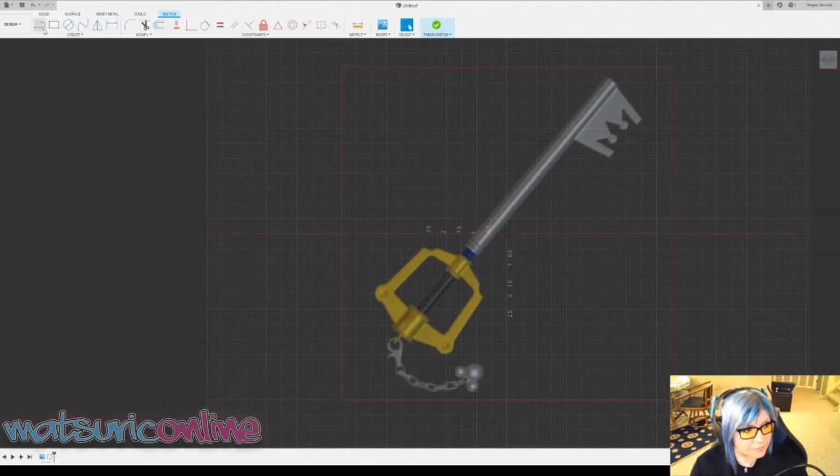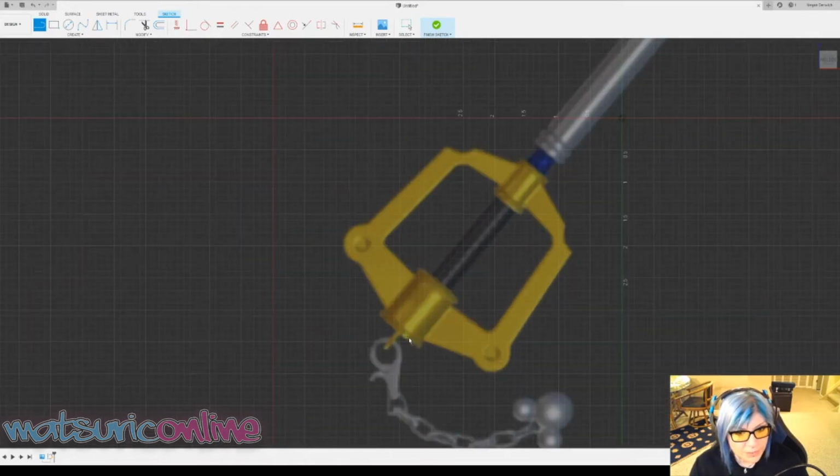Yeah, it's fine. So what I'm going to do is go up to the line function. I'm going to press the line, and then find the center of the part. A lot of times what you'll see with Autodesk is that it's actually pretty smart. It can recognize that there is an edge here in the drawing because of the color shifts, and so you'll see that it snaps to that area.